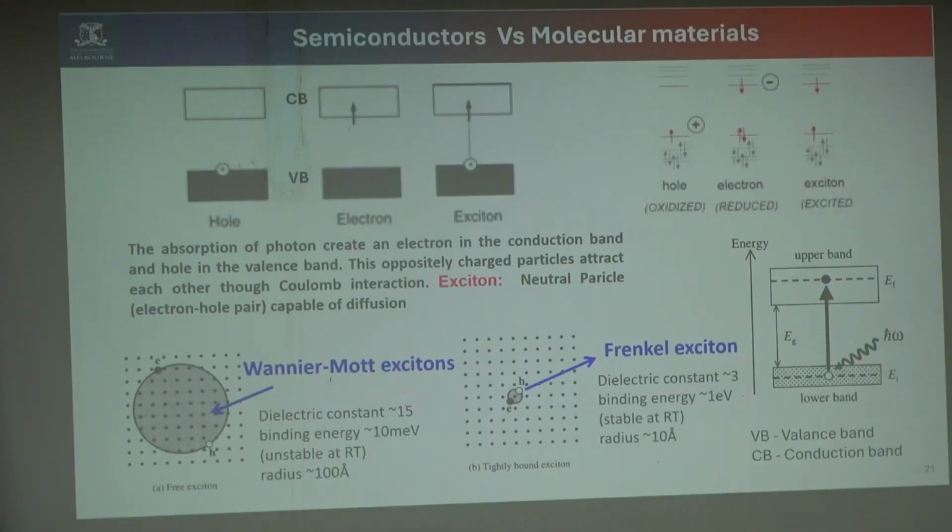So in an exciton both exist. It has both the hole and the electron as still-bound charges. It's separated, but not completely separated. It's still bound, and only then will the electron move out and separate in organic electronic devices. In an OLED, the exciton will combine, and when it combines the energy will be released. The released energy comes out as light. It depends on the band gap of the material.